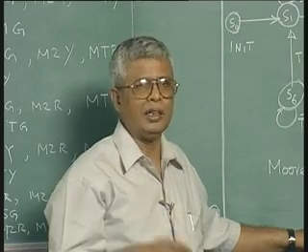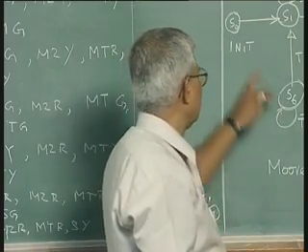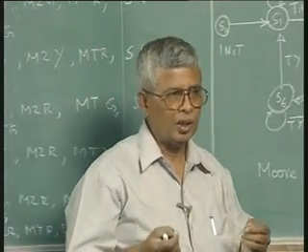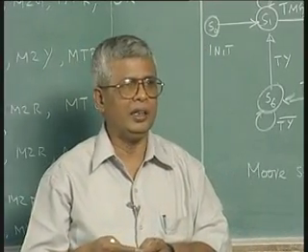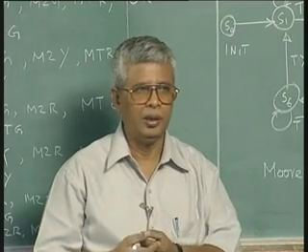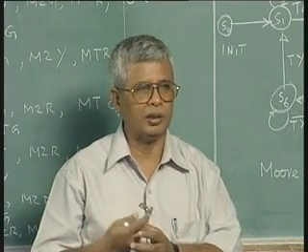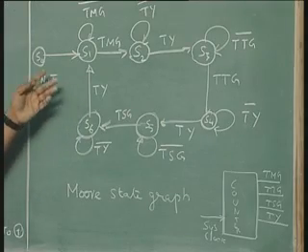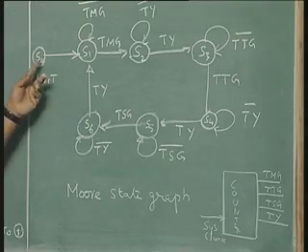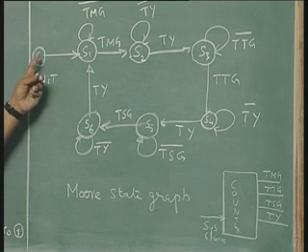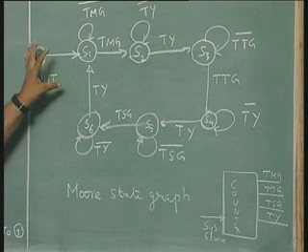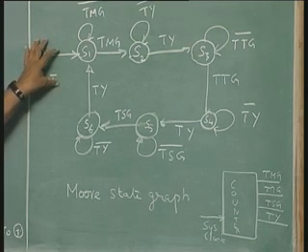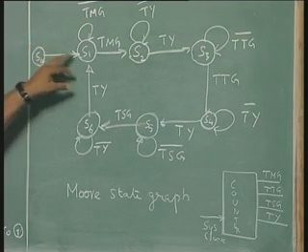So you want to put all those conditions. You can introduce an extra state called init state. This could be the state in which the circuit is switched on for the first time, because we are going to finally have flip flops to implement. The flip flops can be 0 or 1, whatever combination, so you will find them in any of these combinations. Make sure that as soon as you put a reset state, from that state it goes to S1. So this initial state is an optional state, you do not have to have it. In the initial state you can have some blinking condition or whatever condition, remember it goes here.